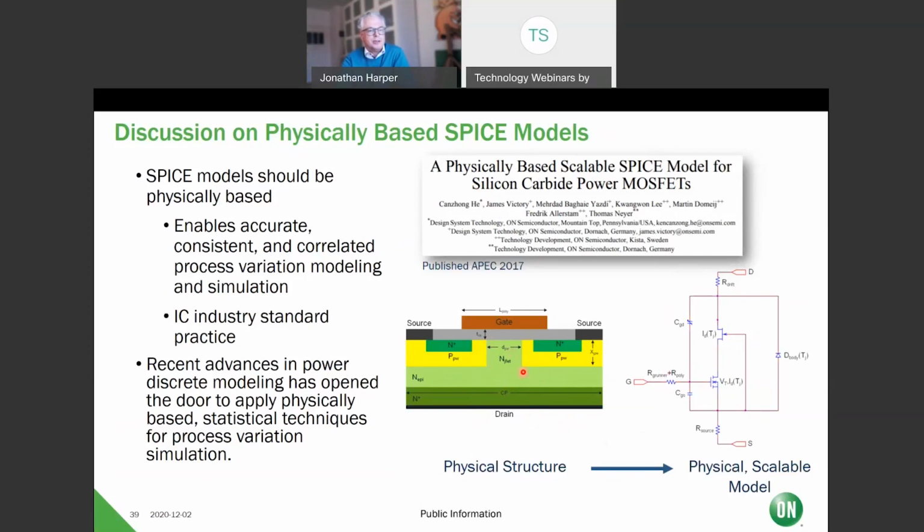In simple terms, it doesn't use a SPICE model as a standard library. It uses basically a set of equations, and we match the parameters of those equations to what we actually do, right? So it's not just, okay, we think of a few nice equations and stick them in. We use special techniques described in this paper. At one operating point, you use a reverse matrix operation to define the different parameters based on the observable parameters you have. So it's quite a complicated principle, but we can also do process variations on this.